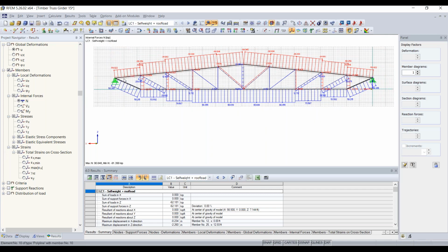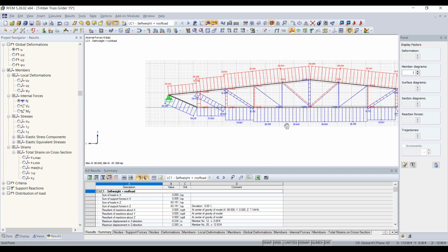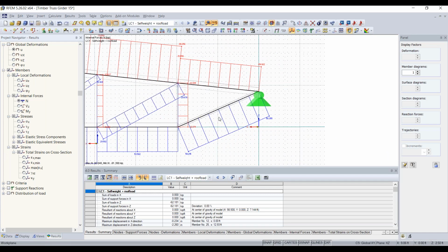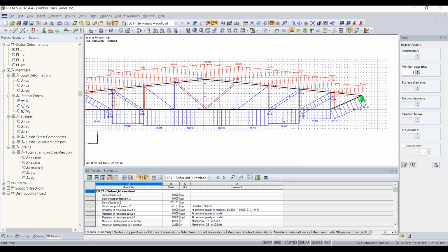You can also take a look and see, and this is important to point out, that we have very high forces on our outside diagonal members here, which I did on purpose. So I can show you later how to optimize these, since these will be critical members, since their cross section is a lot smaller than the main cross sections that we created for our bottom chord here, and they don't really compare too much in size with the bottom chord and the tension forces that it's receiving.